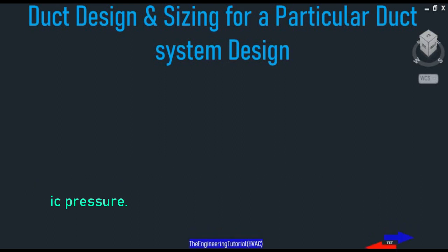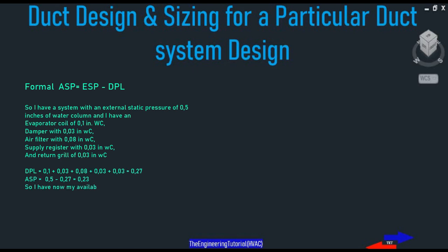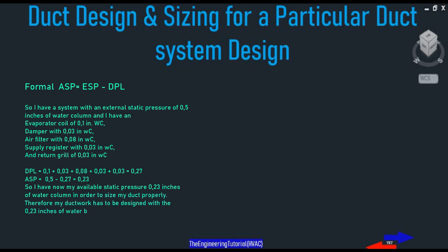For example, if I have a system with an external static pressure of 0.5 inch of water column, an evaporator coil of 0.1 inch of water column, dampers with 0.03, filter with 0.08, supply registers with 0.03, and return grills with 0.03, that gives us 0.1 plus 0.03 plus 0.08 plus 0.03 plus 0.03, which is 0.27.